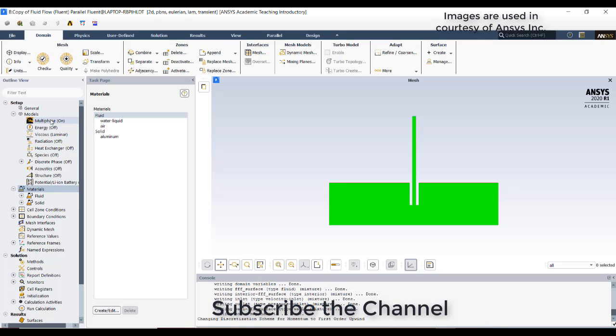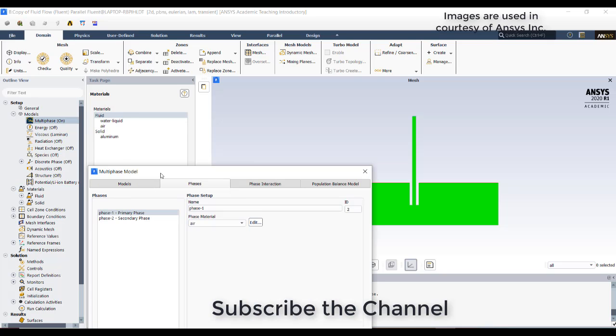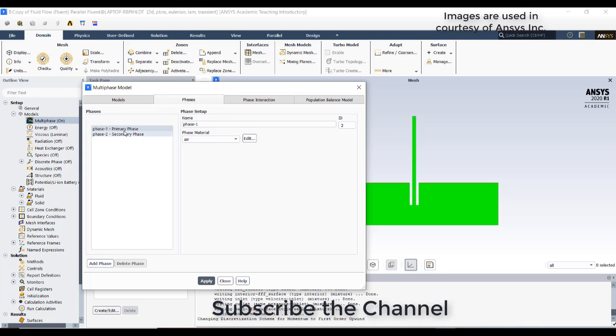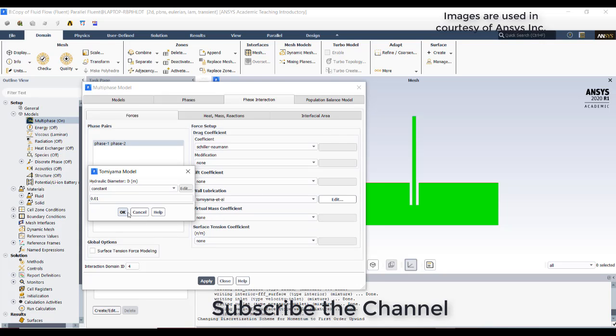So go to multiphase. In phase 1, give air as the fluid. In phase 2, it is water liquid. The phase interactions you can just leave. Maybe here you can just give Tomiyama et al. The hydraulic diameter, I think, is not necessary here.